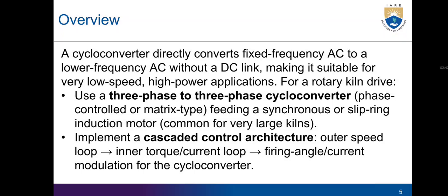Overview: a cycloconverter directly converts fixed frequency AC to a lower frequency AC without a DC link, making it suitable for very low speed and high torque applications.